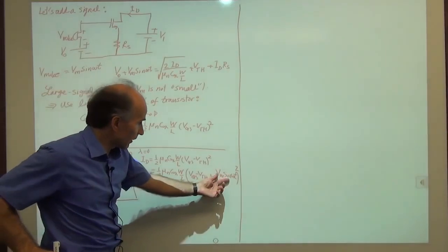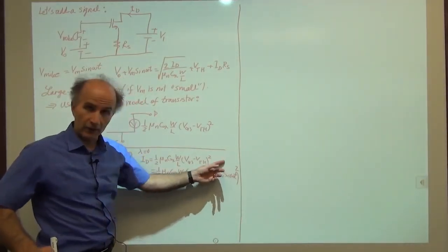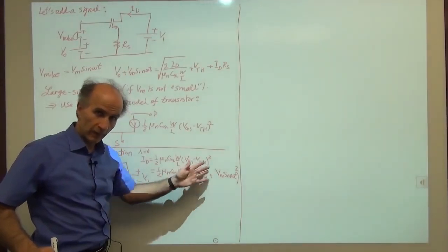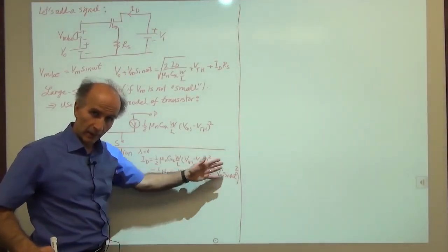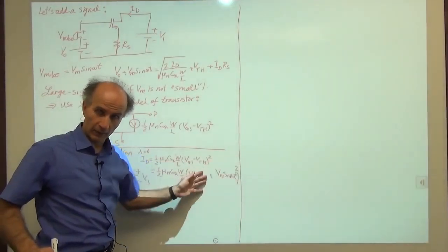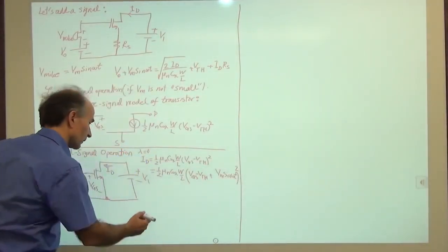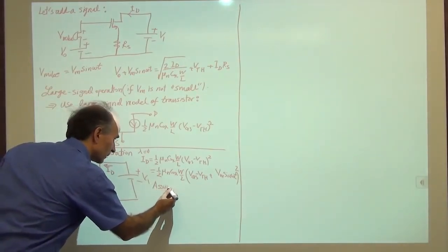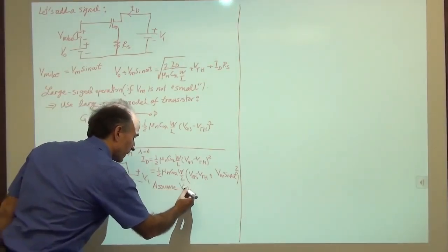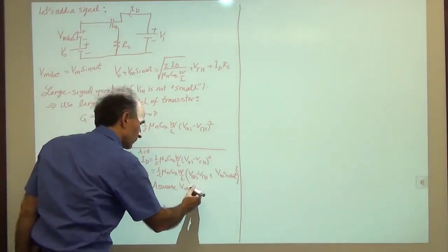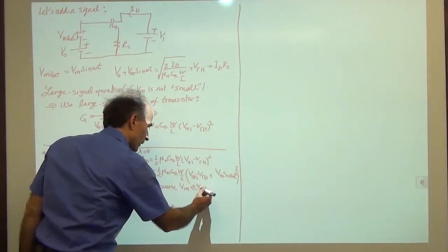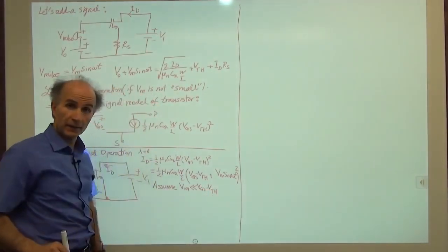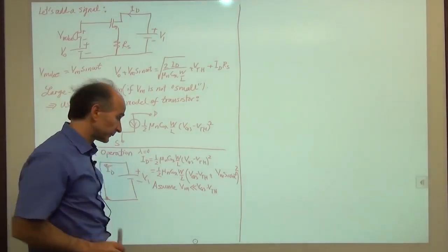All right, so if Vm is small, what's our first reaction here? Well, maybe I can factor out VGS minus VTH to get 1 plus a small number, and then expand that using a simple approximation. Okay, so we will write this. So we say, assume Vm is much less than VGS minus VTH. And that tells us now what we mean by small.